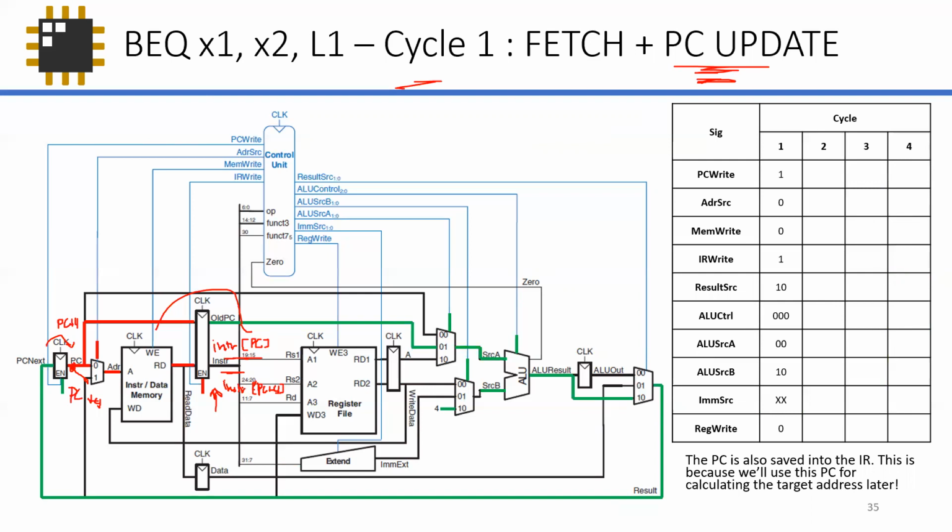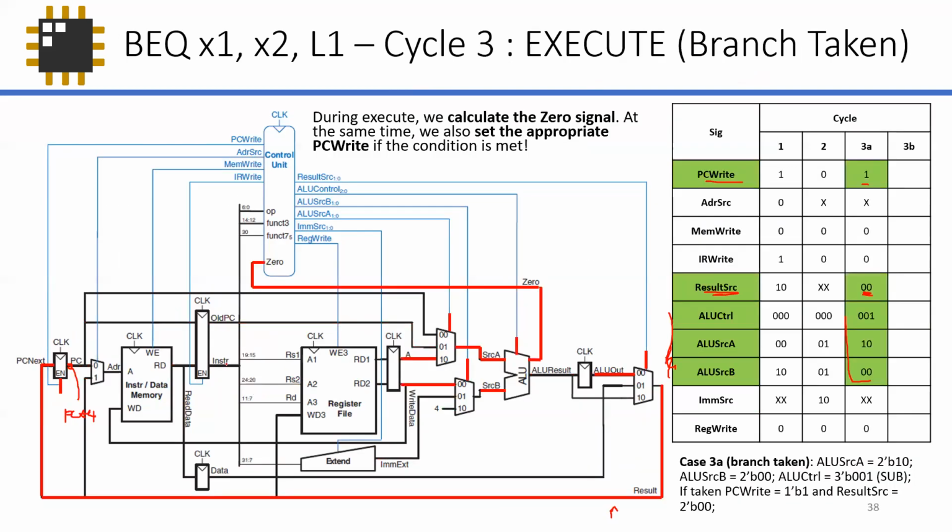Basically, oh yeah, right. Whoever thought of it was a genius, right? That hey, in the fetch state, let's do the fetch and the PC update at the same time. So since we're not really updating my PC, but my PC plus 4 is already ready, the next time you go to cycle 1 or the fetch and update stage again, you're actually looking at the PC plus 4 already. So yes, whoever thought of it is a genius.